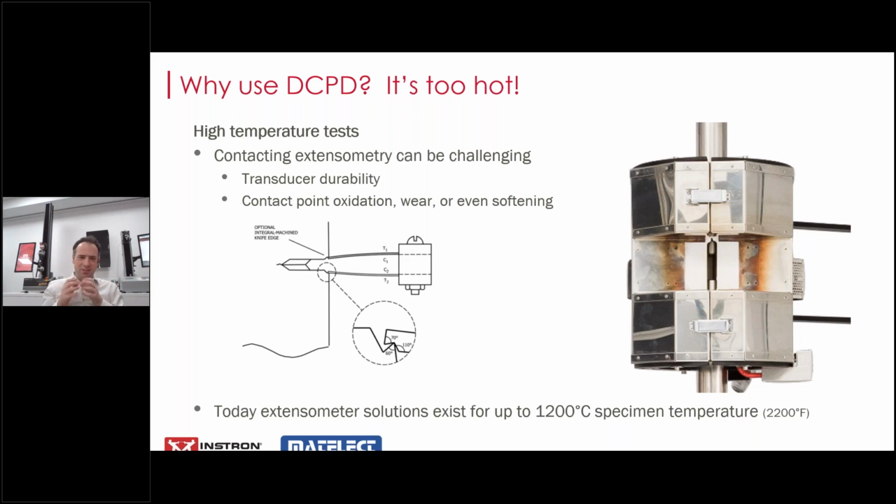That does not mean that it's necessarily a good idea, especially when you're doing something like a crack growth test, which is going to take some time. You can have issues of the transducer durability, and you can have issues of the contact point. Using the traditional methods for crack growth studies, you have a very sharp knife edge. And when you're at temperature for several hours, if it's very high temperature, then you are going to have some serious issues which you wouldn't worry about at ambient temperature.